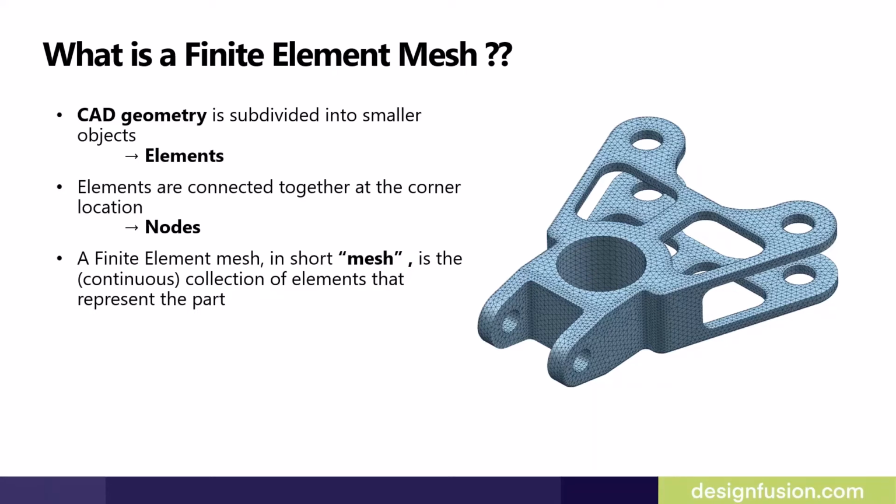We also have to make sure that we do not have any drastic change in the element size, because it will lead to a wrong result. And the people who are doing structural analysis and stress analysis know that discontinuity leads to higher stress in those areas. So we need a well distributed mesh around those areas.